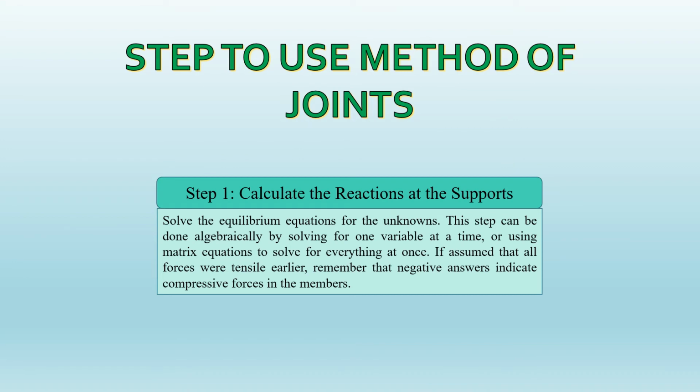The first step, calculate the reaction at the support. First, you need to solve the equilibrium equation for the unknown. This step can be done algebraically by solving for one variable at a time, or using matrix equation to solve for everything at once. If you assume that all forces were tensile earlier, remember that a negative answer indicates compressive forces in the member.